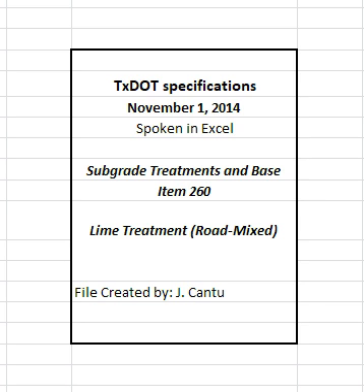4.4 Mixing. Begin mixing within 6 hours of application of lime. Hydrated lime exposed to the open air for 6 hours or more between application and mixing, or that experiences excessive loss due to washing or blowing, will not be accepted for payment. Thoroughly mix the material and lime using approved equipment.